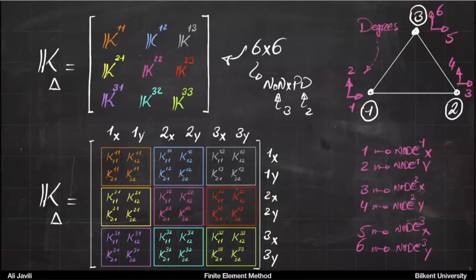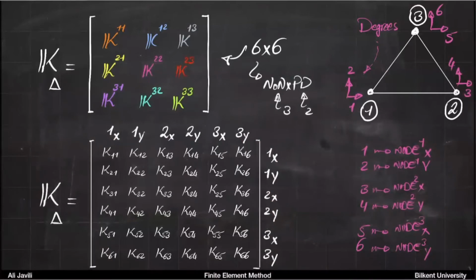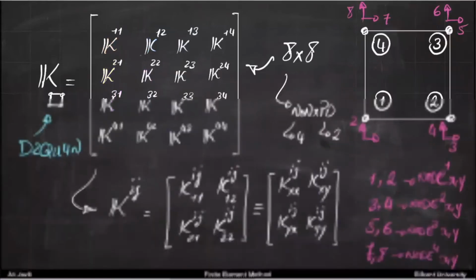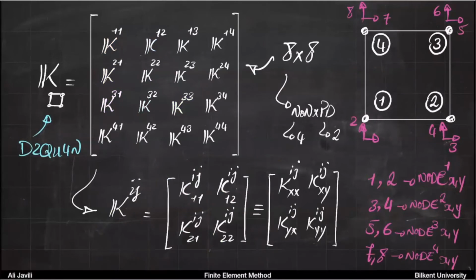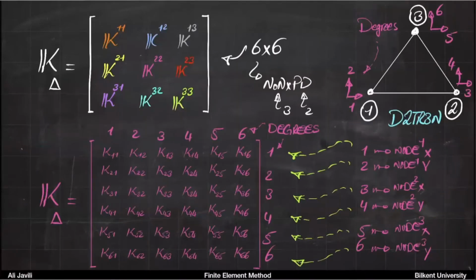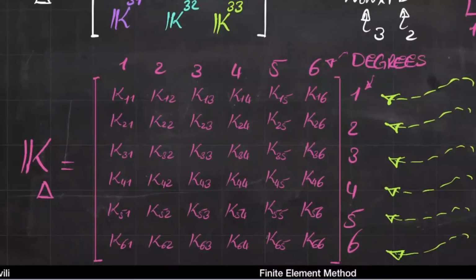Okay, so we use this property and we write these based on this numbering, and then you would see basically this one. Okay, now in this picture you have a usual stiffness matrix as you would have always before. Then you don't have to worry about the superscripts or subscripts or the dimension of the problem. Now it's a matrix. It's a 6 by 6 matrix. Okay, and then you just construct this at each element.